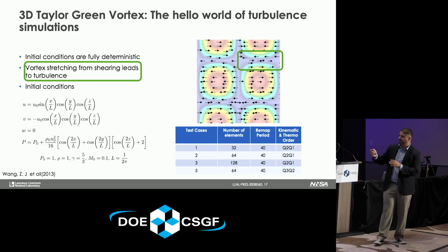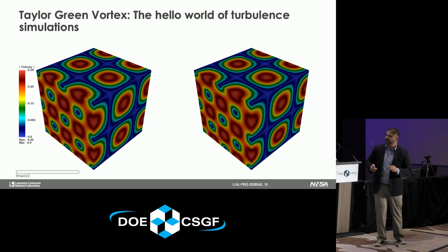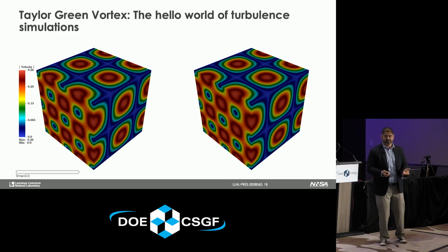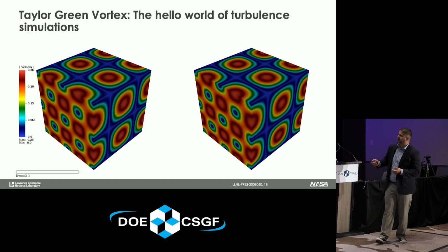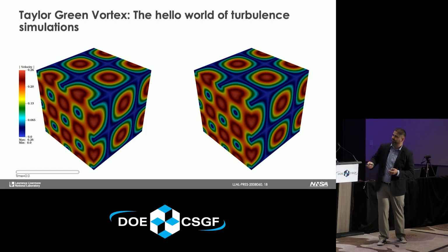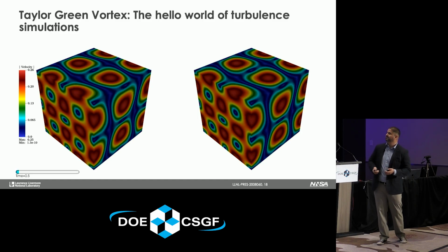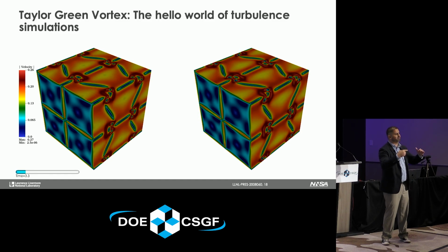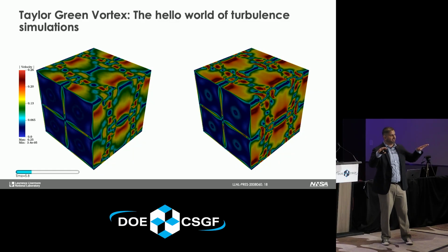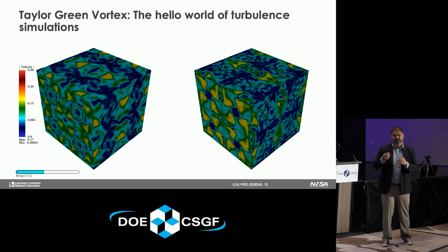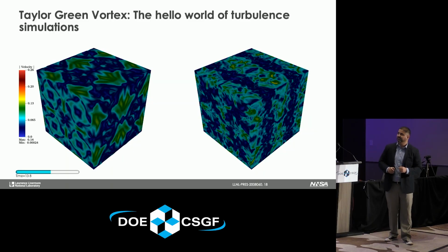Right, so I did a basic grid convergence study here. Very similar to the previous simulation, this is the velocity field, set up on a triply periodic cube. In this test case, I doubled the grid resolution with respect to this one. As a result, you should see more turbulent structures. This is a decaying problem. I start off with a certain amount of kinetic energy, and as the problem destabilizes, it's going to transition, and then towards the end is full-blown turbulence.